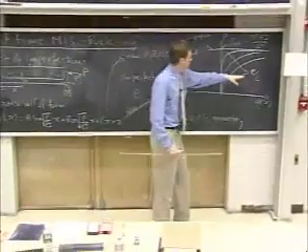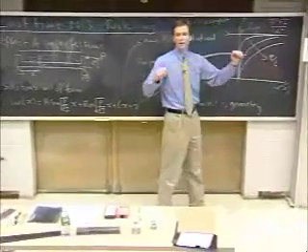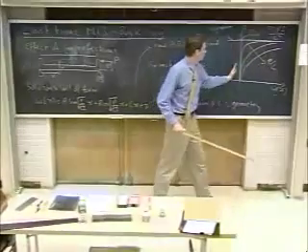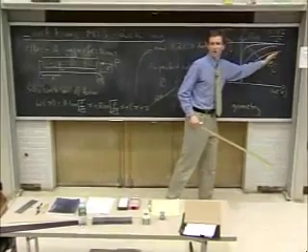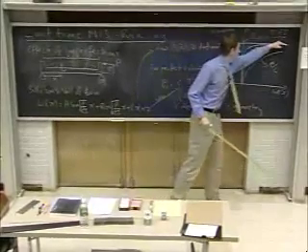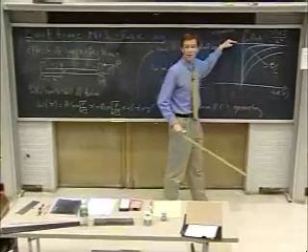And depending on how non-straight, how eccentrically loaded our column is, we'll get a larger and larger deflection at a lower and lower load. But the bifurcation behavior still represents an asymptote.